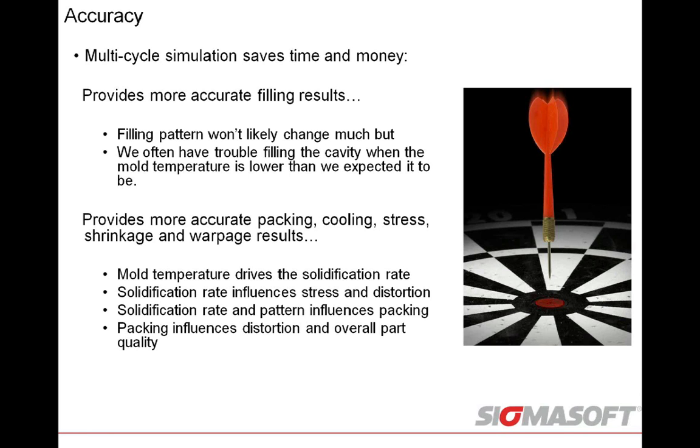And then more importantly, where you really see the benefit is in the packing and cooling phases, and then the resulting stress, shrinkage, and warpage predictions. So your mold temperature is very important. And this is one of the strongest things within SIGMASOFT that we can't talk about enough. It's one thing to simulate your part geometry. There's a lot of value there.